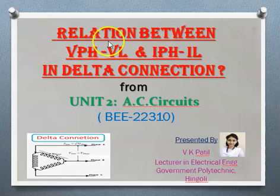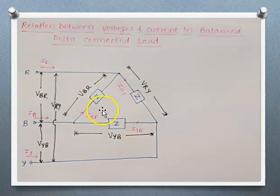Today we are going to discuss the relation between line voltage, phase voltage, line current, and phase current in case of delta connection. Previously we have discussed this relation in case of star connection. So let's get started with delta connection. Here a three-phase delta connected balanced load is taken where the impedance of each phase is Z ohm. Now let's identify where line voltages and phase voltages are marked.